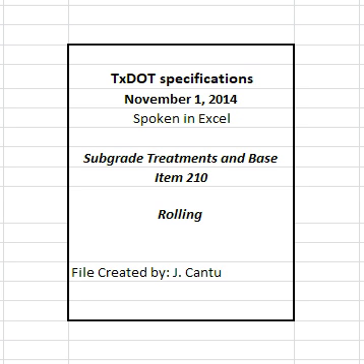2.4 Pneumatic tire rollers. Pneumatic tire rollers consist of rubber tire wheels on axles mounted in a frame with either a loading platform or body suitable for ballast loading. Arrange the rear tires to cover the gaps between adjacent tires of the forward group. Furnish rollers capable of forward and backward motion. Compact asphalt pavements and surface treatments with the roller equipped with smooth tread tires. Compact without damaging the surface. Moisten the wheels with water or an approved asphalt release agent when necessary.